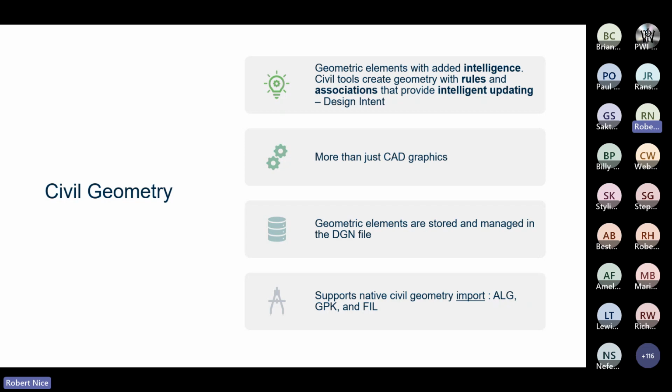I modify, I don't know, I go and change the curve or something, and depending on what locks you've got turned on, like right lock or pen and pencil and stuff, it would either update or not. But you could delete all the graphics, because as long as you saved the ALG, of course, you are happy. Now everything is in the DGN. Everything is managed by the DGN. So this design intent is clever, but it's all inside the DGN now.